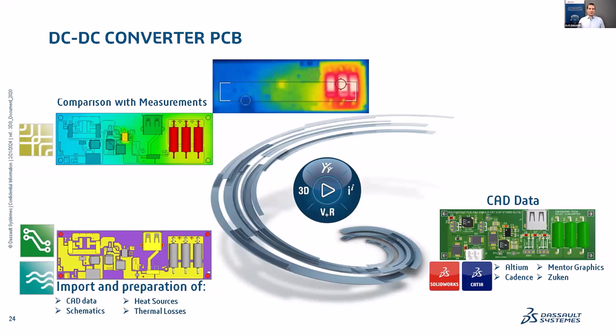The ECAD data was imported and used for an IR drop simulation. Then we performed a thermal simulation with the resulting losses. We also did a 3D EM simulation, because with the IR drop we can, of course, not take into account switching losses. Then another thermal simulation was run with that 3D EM simulation and the transient task that was run in there. The case including switching losses was indeed very close to the measurement results, despite the simplifications used on the board in order to allow for a fast evaluation of the temperature.